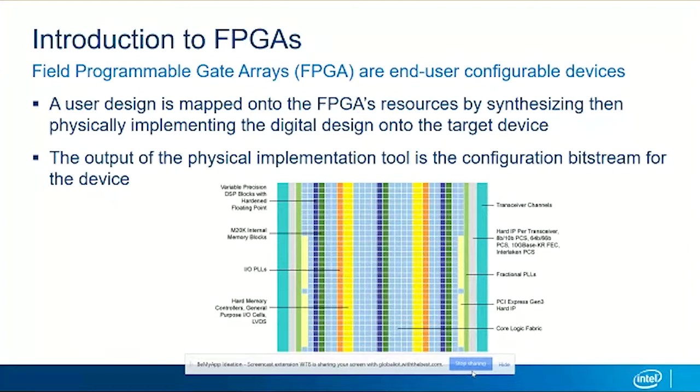The diagram that we show is from one of the Intel Arria 10 devices. The reason I'm showing this is very important in that how the design is mapped to the logic will impact, one, the performance of the design that you implement, two, how long it takes to reconfigure the design, and three, it'll also impact how you can verify the design. So it's really the mapping of the design onto this floor plan that is the key to success with partial reconfiguration.